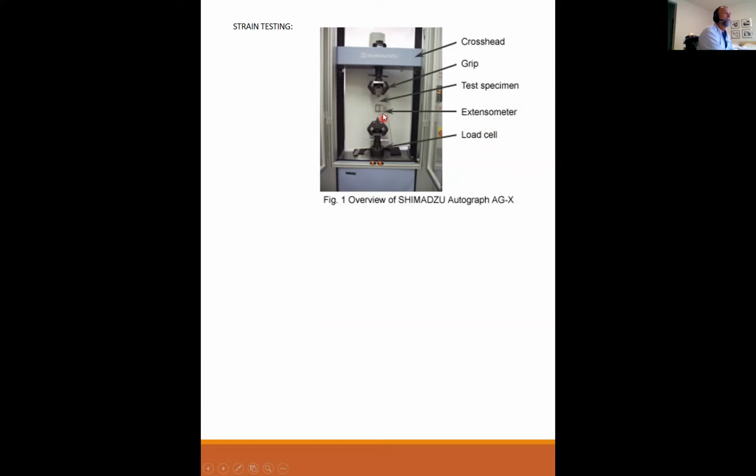An extensometer is something very sensitive that can measure the stretching action between the 2 points. You plug into the computer the cross-sectional area of the sample. So between what you tell it for area and the load cell, it knows stress. And then it gets to strain by measuring the stretching between a known distance.